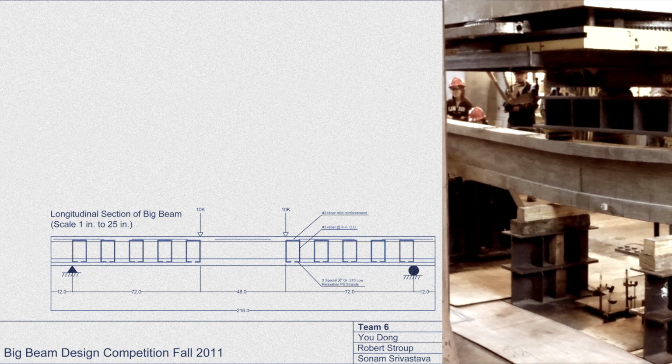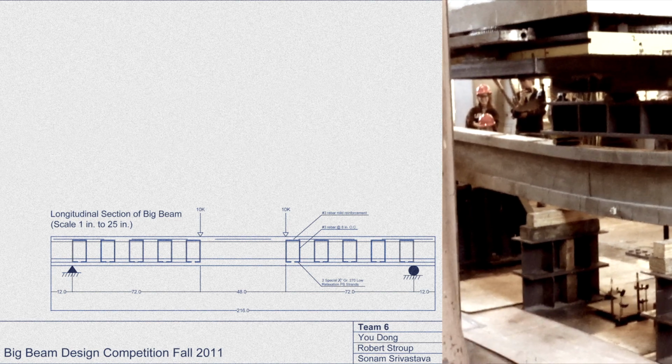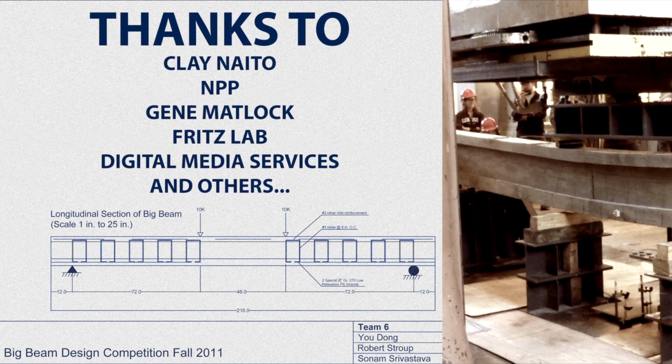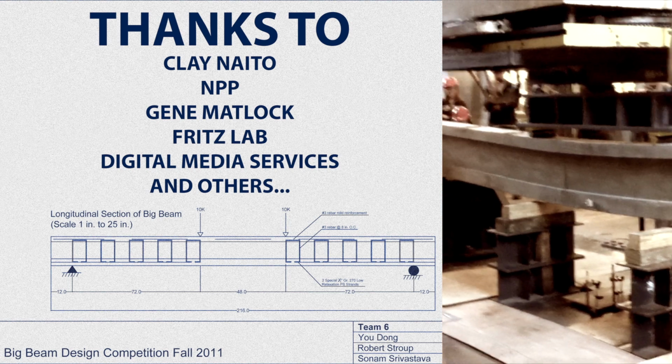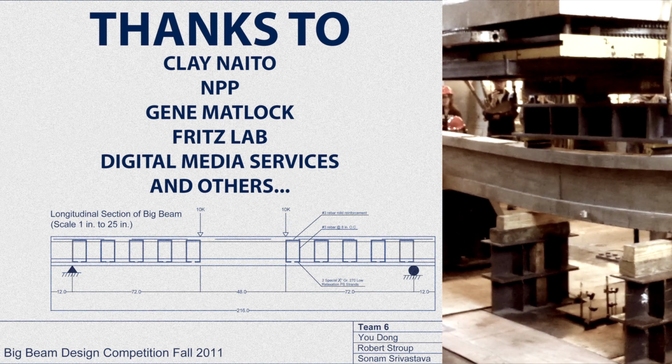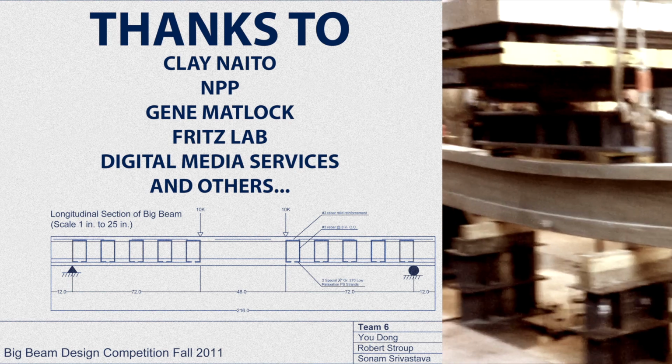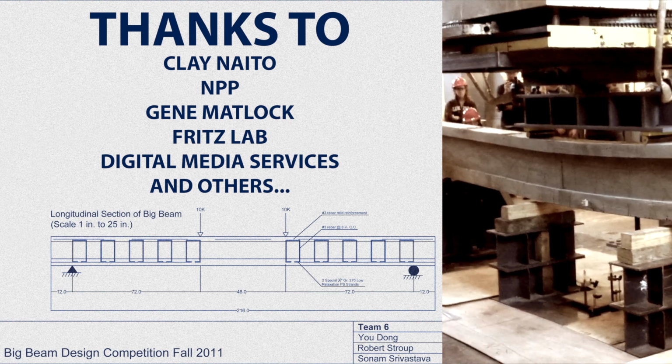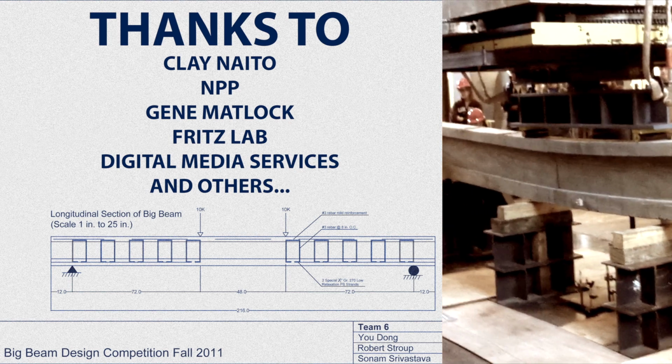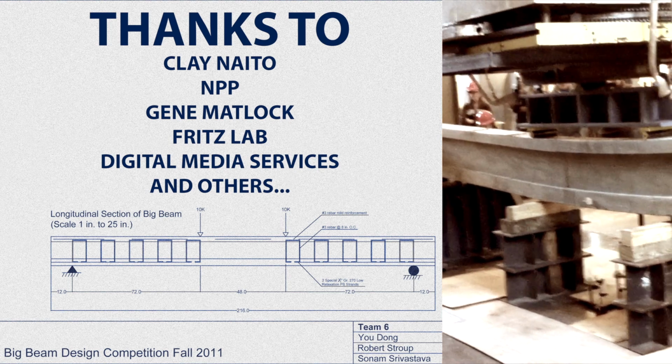Lastly, we determined the governing deflections per ACI by finding the strains at the topmost and bottommost fibers in the midspan of the beam. We calculated these deflections at 4 different points in time: 1, the initial loading, 2, the placement of service loads, 3, the cracking stage, and 4, when the nominal load would be reached.